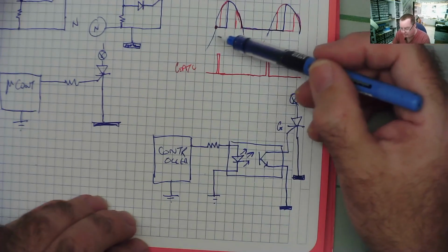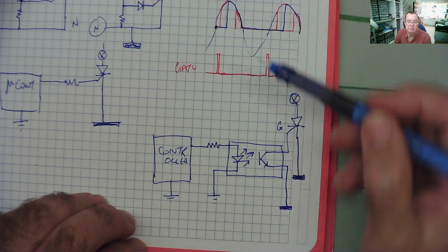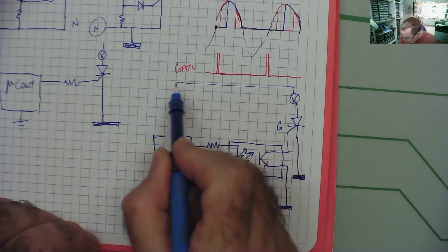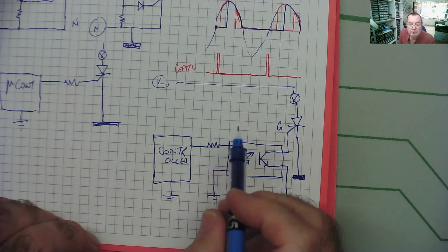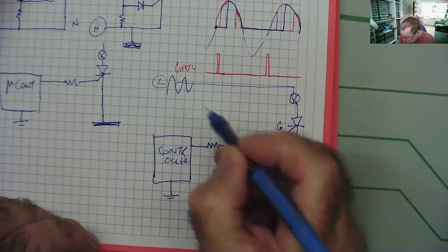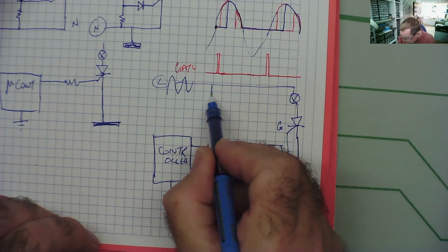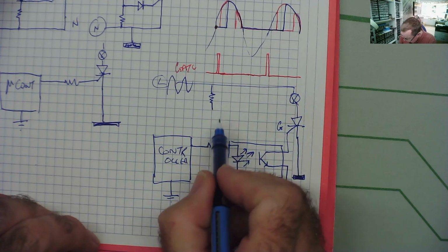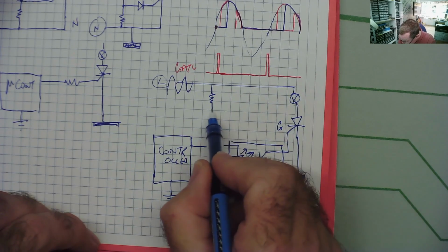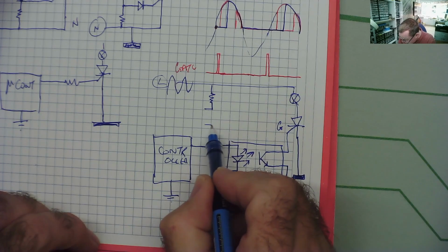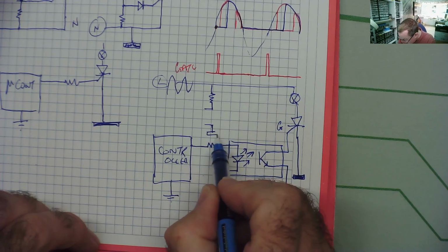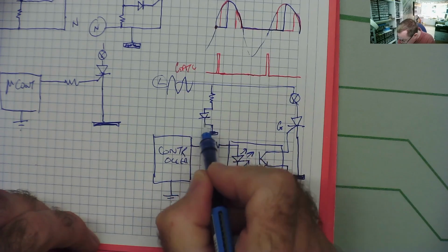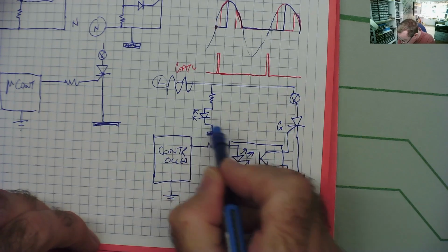Also, you probably want to monitor the 0 crossing point. So what you will do is, this is effectively the other side of the load, this is your live, this is AC. You will have from here a resistor to another opto-isolator, wired the other way around. So this is hot ground, resistor in there, this is the LED.